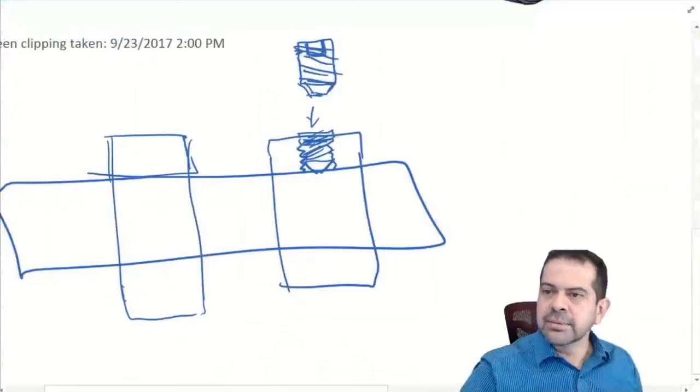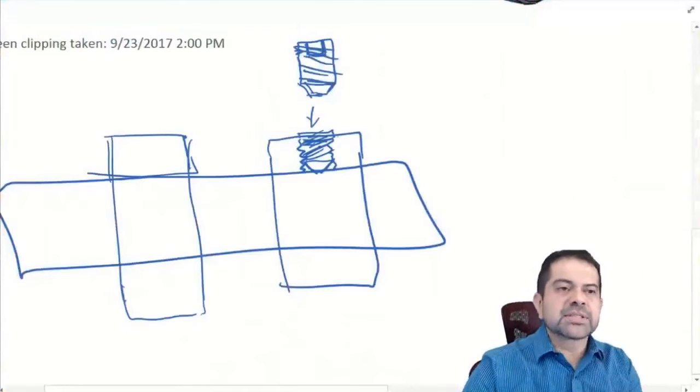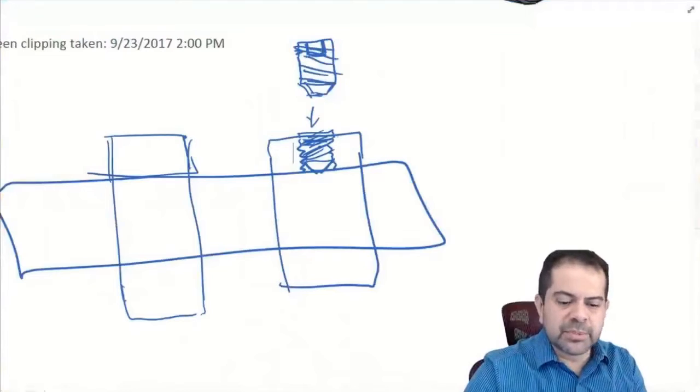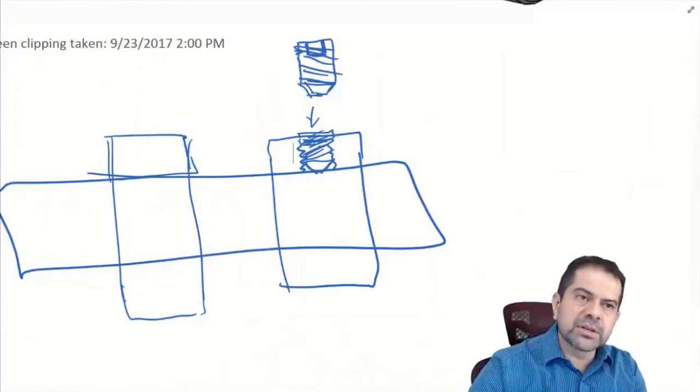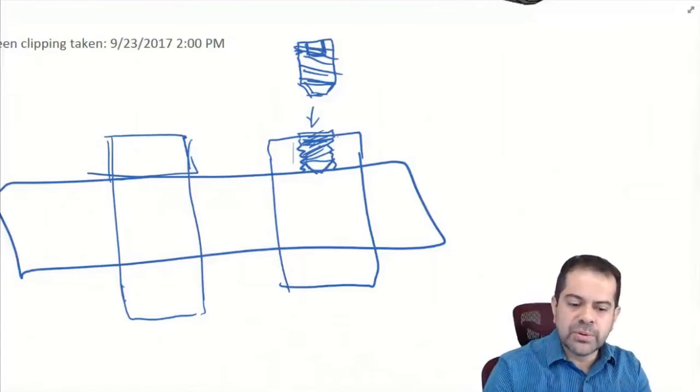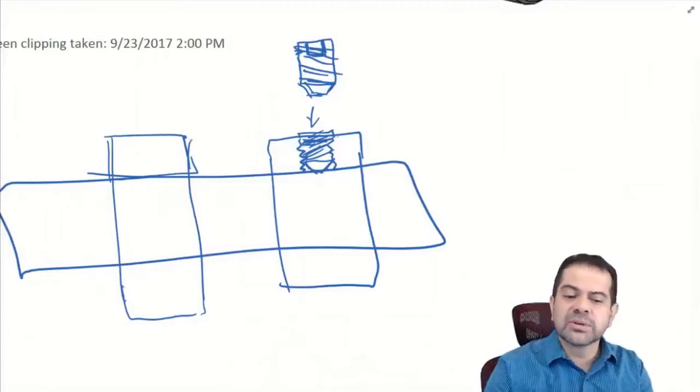And yeah, there are a number of things that are wrong with this approach. And Camila is absolutely correct. One of them is that the set screw could loosen. We haven't talked yet about how to secure the external threads of the set screw to the internal threads of the collar. Obviously, a screw is intended for you to be able to turn it. So how do you, when you want it to not turn, how do you prevent that?